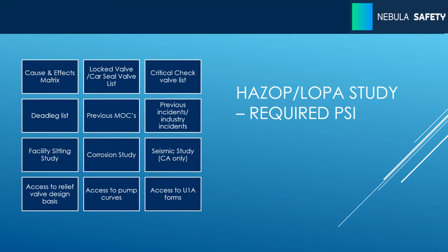I mentioned previously that the PHAs are on a 5-year cycle. So the question is, well, why can't we just do one PHA and it lives forever and you don't have to sit there and put that team together every 5 years? Well, the truth is processes change. You might need more throughput, you might change out your pumps, lines go away, new lines are added. All these things change the process, and a lot of times on just what you would think is an insignificant basis. But collectively, those changes might add up to something that could result in a hazard.